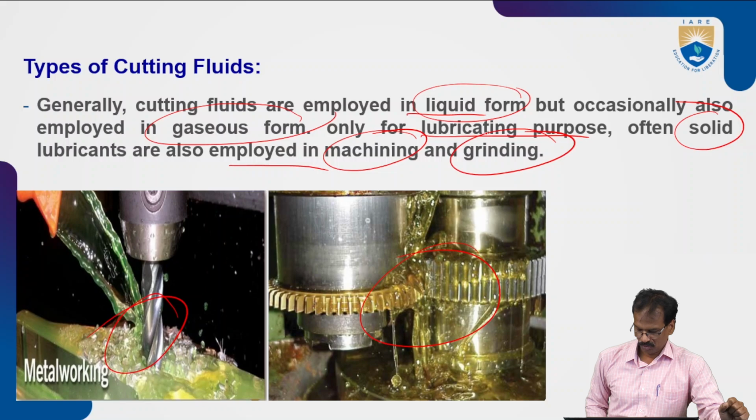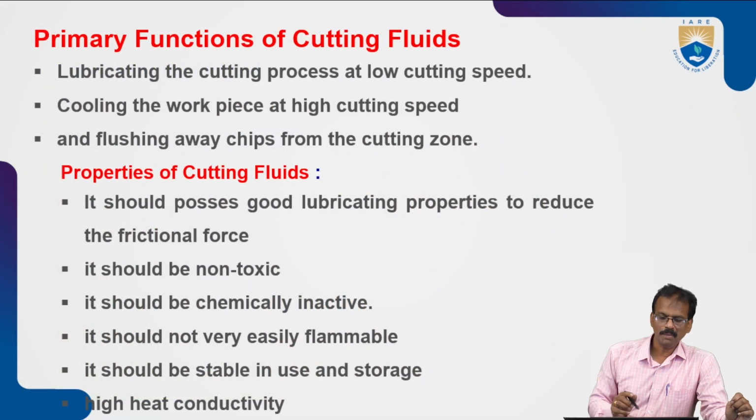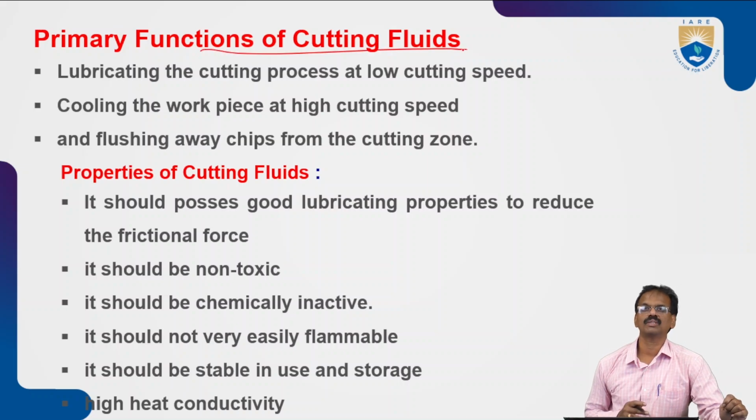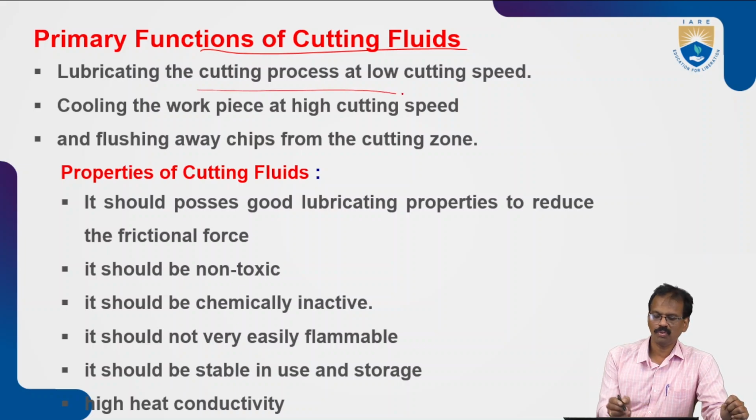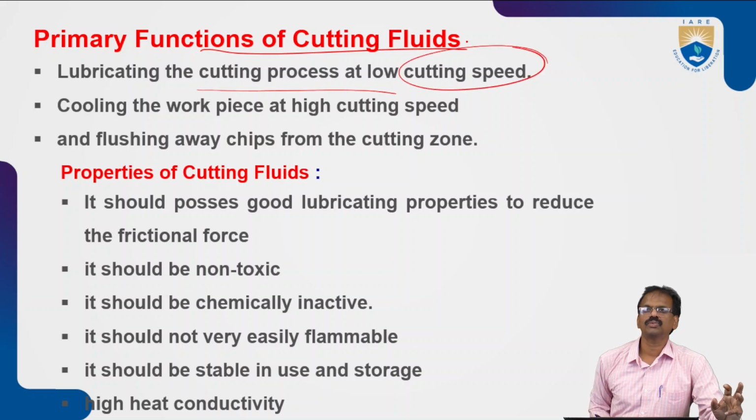Okay, so three types of the cutting fluids. Most of the cutting fluids are in the liquid form. So only in some occasional cases we will use either the gaseous form or solid form. Okay. So the primary functions of the cutting fluids, we will see what are the very important functions of the cutting fluid. Already discussed that one also. Lubricating the cutting process at cutting speed, okay? Just to reduce the friction between the workpiece and the cutting tool.